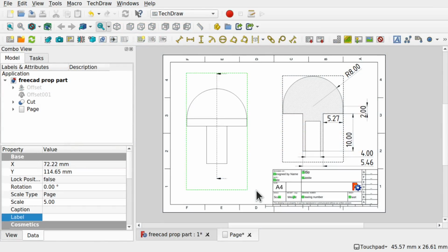So when would I use the part design over the part? Well, considering the part design is a guided process, it's a well-defined process. When I have something like a technical drawing like here, and this is the prop of our previous project without the propeller wings attached to it, then I'll be looking at something like the part design, because I know from this picture here, this drawing, that I can create this shape just from one single revolve. I know I'm not going to go out to other workbenches because I don't need to. I can do what I need to do in the part design in a well-defined manner.